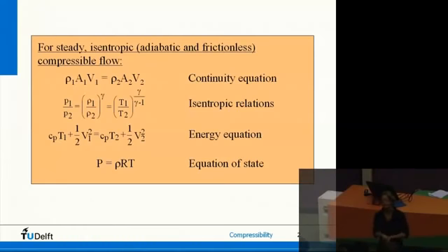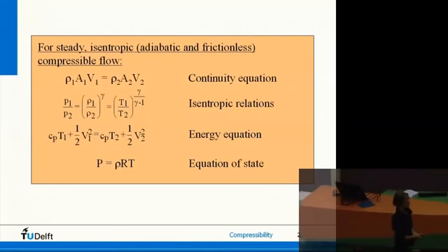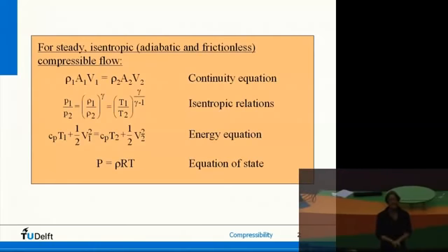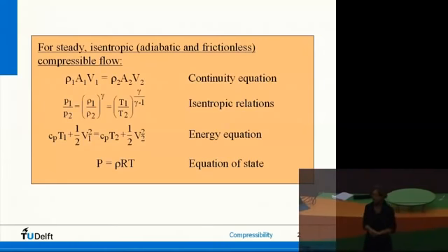Because we were able to derive the equations, but we had to assume isentropic flow. An isentropic flow is adiabatic flow, and that means we don't add heat or extract heat from it. Then how can temperature change? Well, not by adding or subtracting heat, but internally in the flow temperature can change.